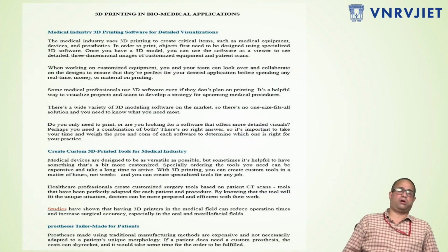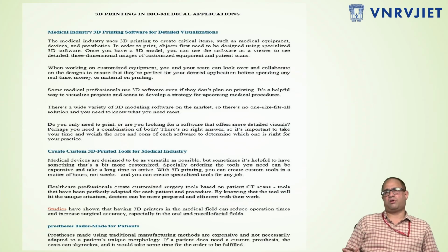So when you go for complex surgeries, your human anatomy is going to differ from others. Based upon your bone structures, your body parts and your anatomy, the parts are going to be calculated, and then the data is taken using CT scans or MRI scans. Using medical modeling software, they construct your parts. After the parts are constructed, they are converted into an STL file, and that STL file is used for 3D printing of the components.